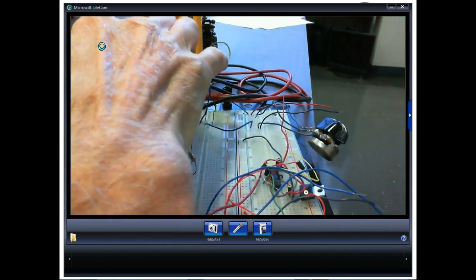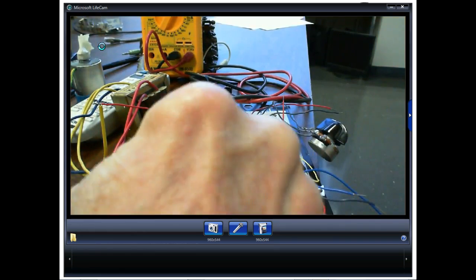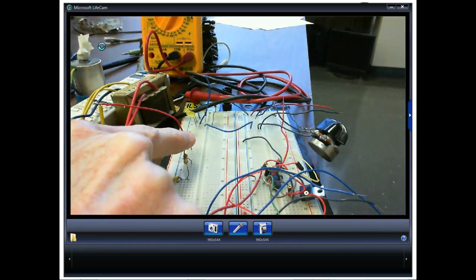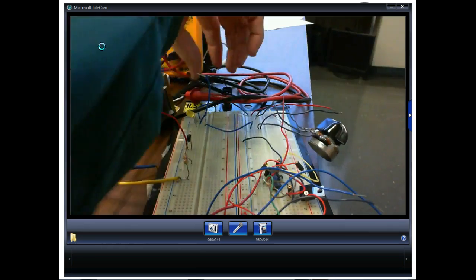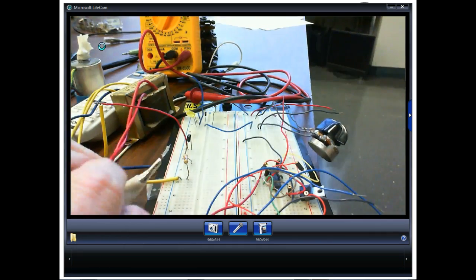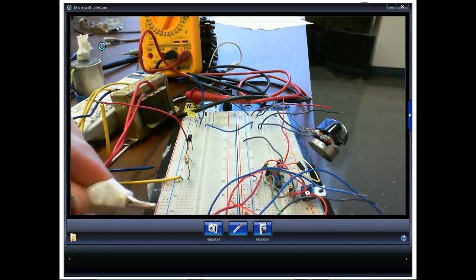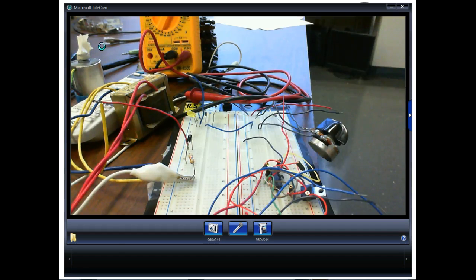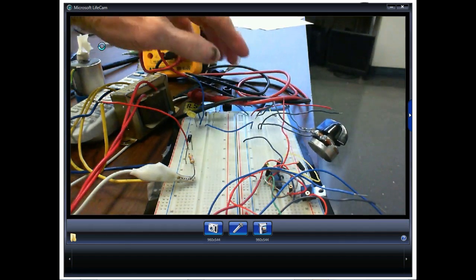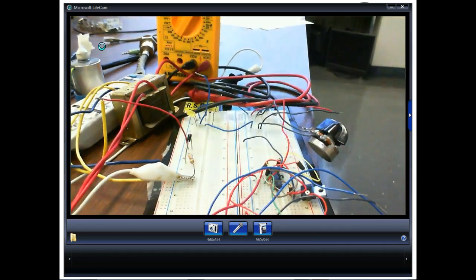Okay. So here's our circuit right here. Very, very simple. Here's the transformer, and I think I showed you the voltage rating and everything on top of it, right? Here's the 1K resistor, brown, black, red. Here's my diode right here. And we're going to measure the output. I've got an alligator clip. We call these alligator jumpers. I don't know if they carry them in the bookstore, but these are real neat for this class. Now, you wouldn't use them in a 2,000 volt circuit, but they work out real well for this class. And we've got our meter on DC. If you don't know what you're measuring, of course, you're supposed to start with the highest range possible, right?